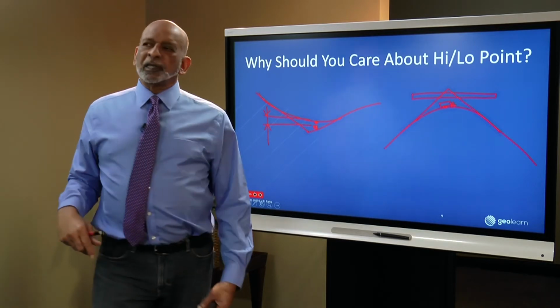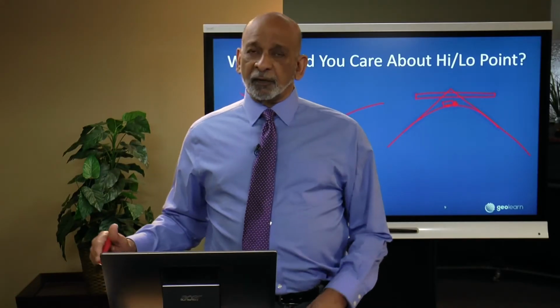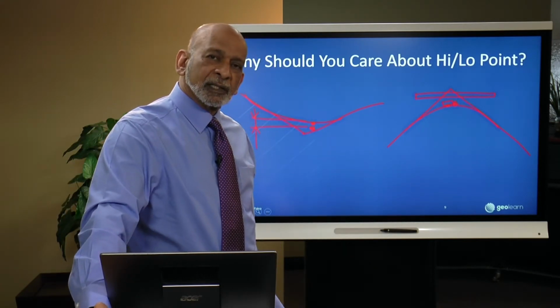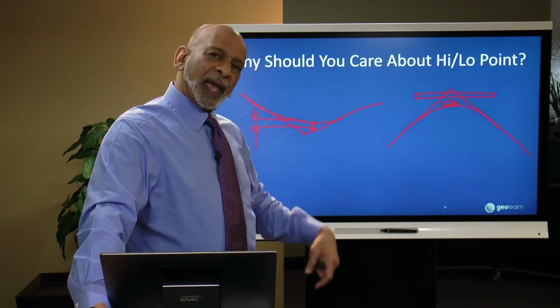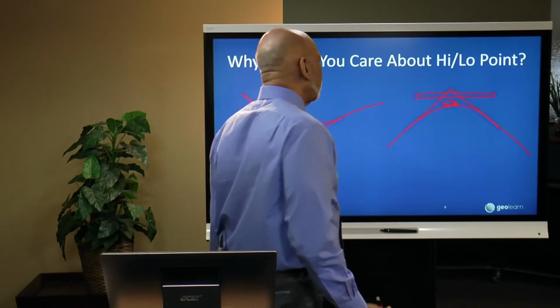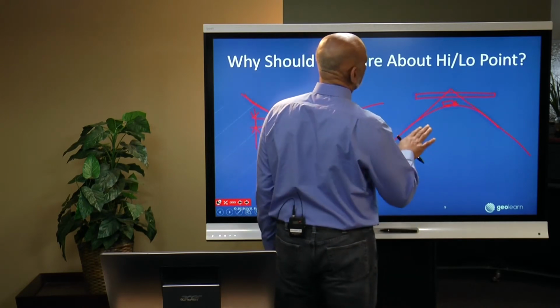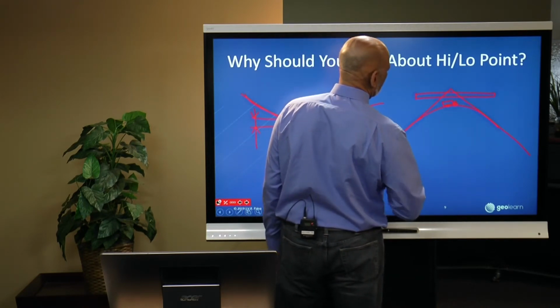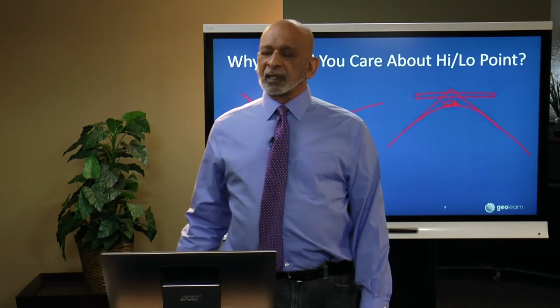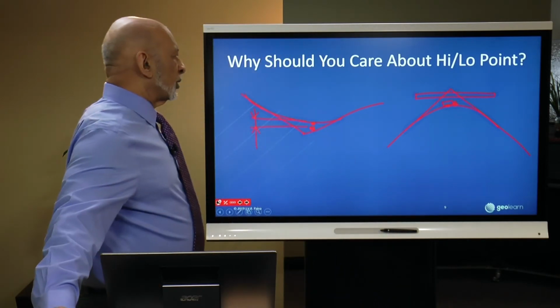And so very often engineers will need to calculate, if the road that they're passing under already exists, they may have to work backwards and figure out what G1 and G2 may need to be, so that they can have a good transition or design a length of curve that's long enough to bring the driving surface down and so forth.